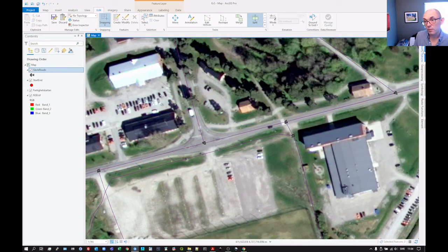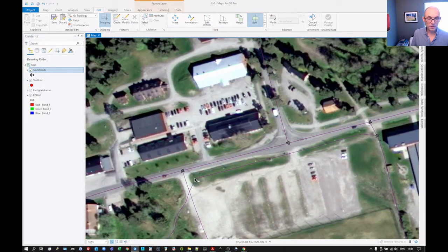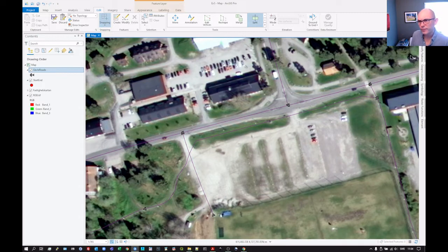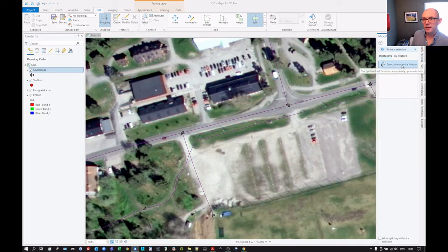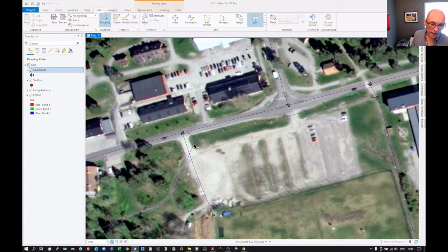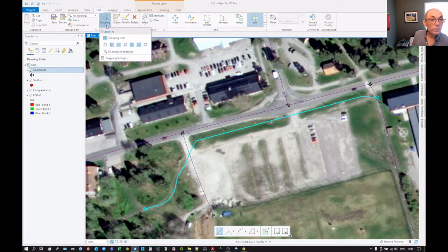So we go back to our modify features tool. Let's just actually move over. There we go. Modify features. Click there. Select to modify, and let's modify that line first. And so that's selected. Now there's a vertex, and well, actually ideally what we wanted, let's turn that vertex, we wanted this, the intersection. Let's see if we can get that to work. So let's turn off all of those and just leave the intersect there.